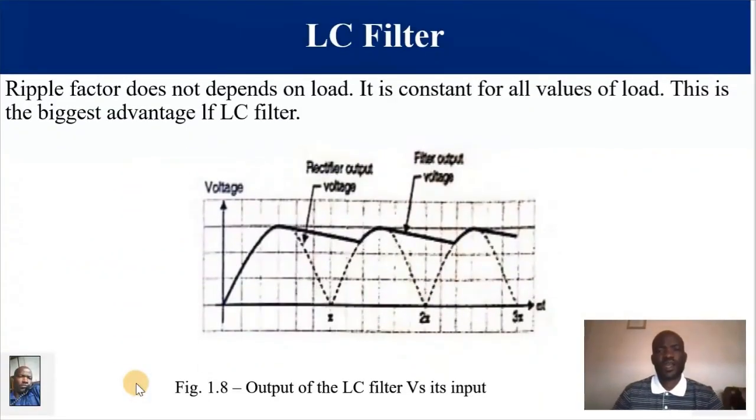LC filter output. This is the waveform diagram. This represents the output of the center tap full wave rectifier, and this is the voltage across the load, which is also the same as the voltage across the capacitor, because the capacitor is connected in parallel with the load. As you can see, we know that AC components change in direction as well as in amplitude.